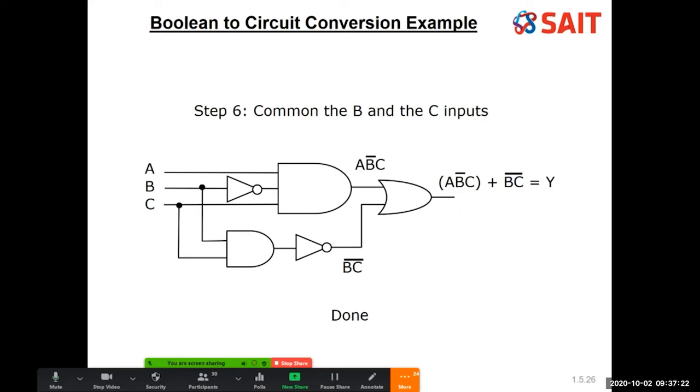So the simple method of doing this is to start from the output. Baby steps. An output, well, that's a single output. What sort of gate is it output from? And start breaking the equation down in those logical places. It's an OR gate. It's got two inputs, etc. I just work through those series of small steps and I can create a schematic from the equation. Okay.